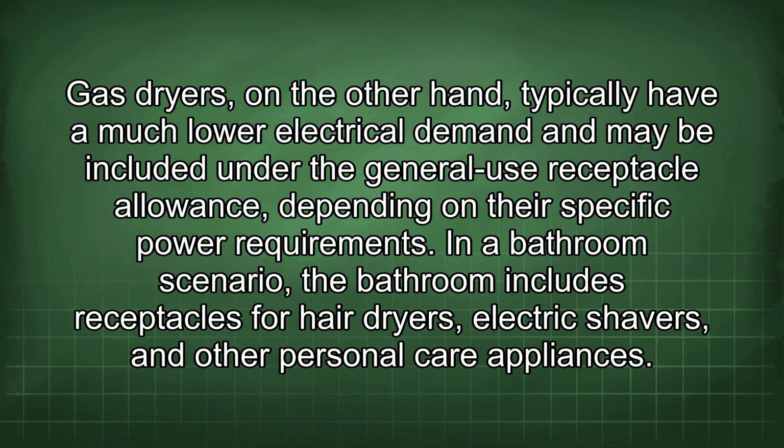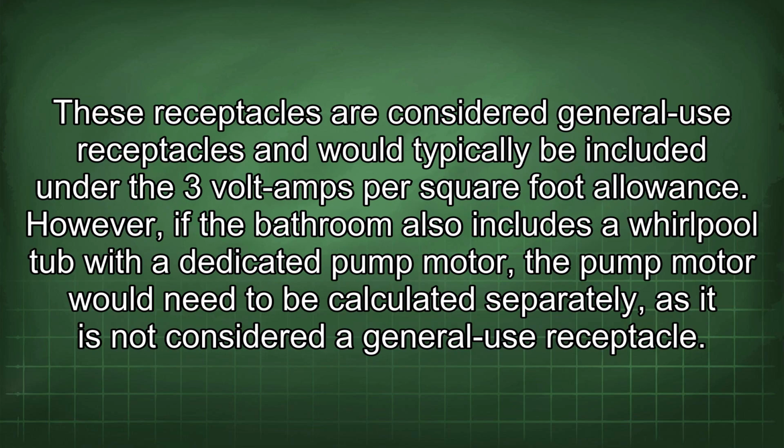In a bathroom scenario, the bathroom includes receptacles for hair dryers, electric shavers, and other personal care appliances. These receptacles are considered general use receptacles and would typically be included under the 3 volt amps per square foot allowance.